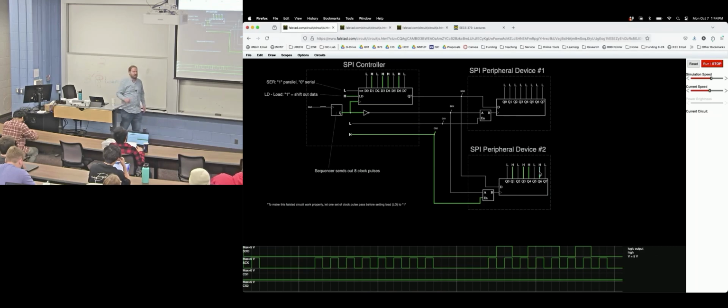So you'll find with a lot of these bus protocols that they're so primitive. I mean, you're looking at waveforms where you actually have to discuss a priori with the receiver and transmitter what the format of that data is. Is it going to be 8 bits? Is it going to be most significant first, least significant first? All those sorts of things. It's different than, say, USB or USB 3, which is a much more complicated protocol, and all that's already predefined. But it's less flexible in that sense.